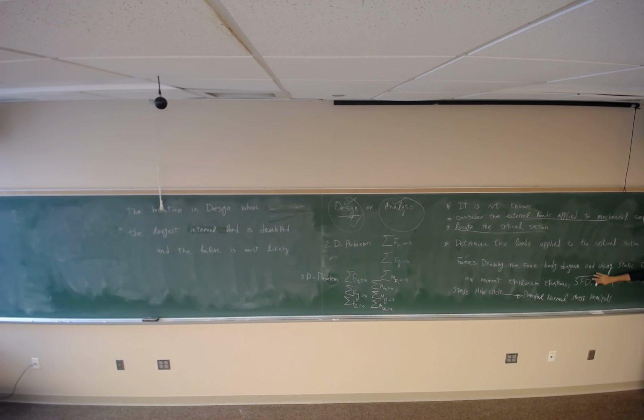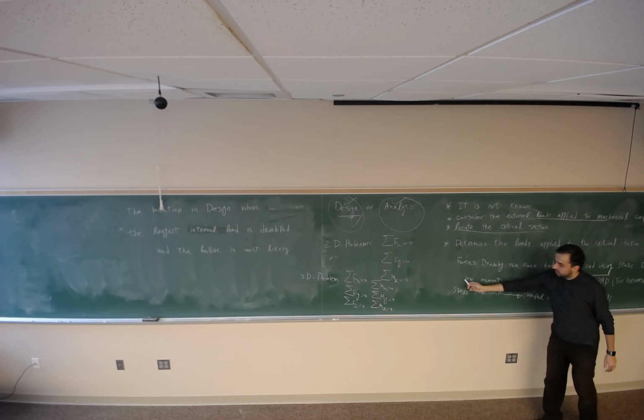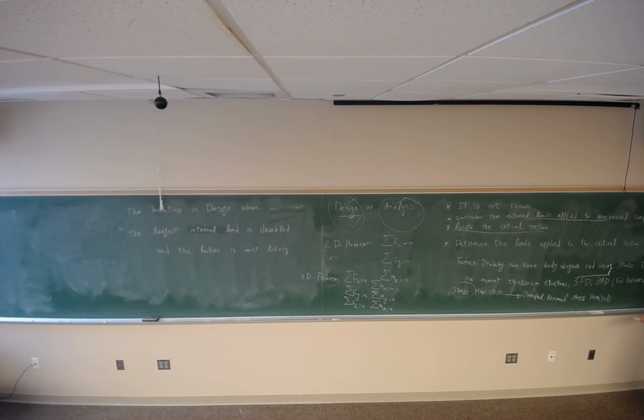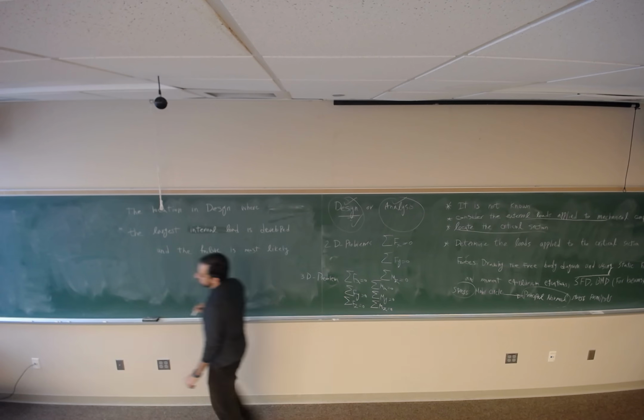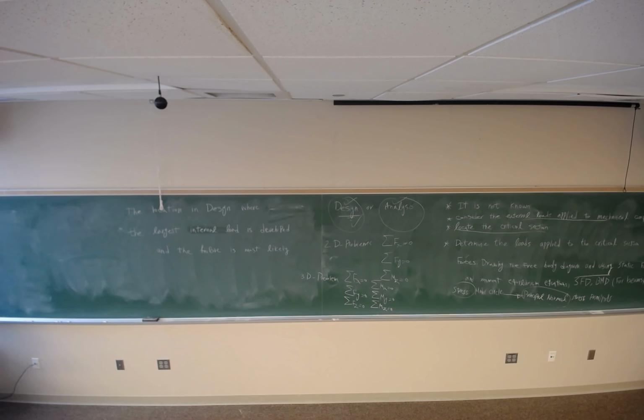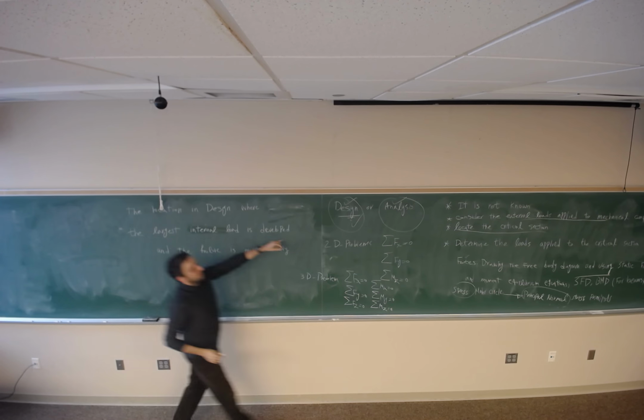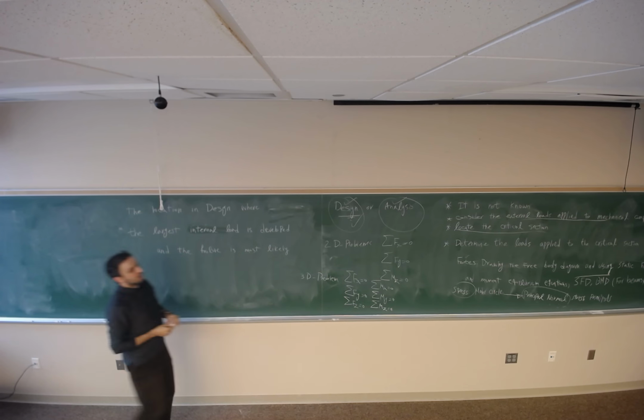After you find the forces and moments, you can calculate the stress. After you find the stress, you apply the Mohr circle to find the principal normal stress. And then you can answer the question if failure occurs, or if you want to design, you can finish your design and size the dimensions of the mechanical component.